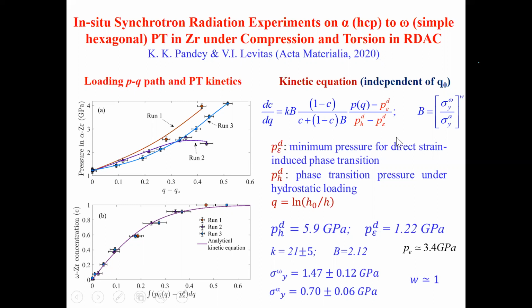So this drastically simplifies. Then yield strengths are not a function of plastic strain, and we can indeed obtain such a simple equation. Now, what is also important, what we found: we used different magnitudes of preliminary plastic deformation before phase transition, but results are independent of this. This is also very important. It should be higher than a critical value to reach this saturation of the hardening state, but then behavior is independent of preliminary plastic deformation.